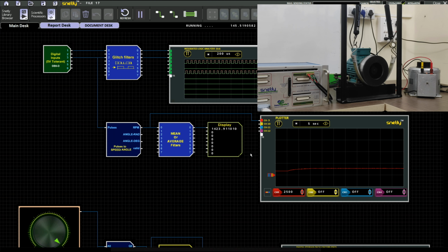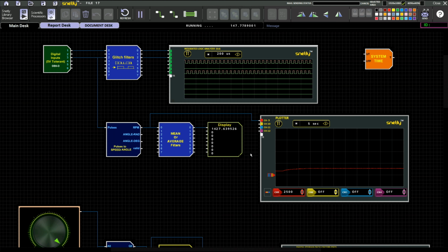Now the application is running in real time. We can observe here the encoder signal as well as the speed of the motor, your reference signal and the current waveform of the particular application we are using. Here we are using a 3-phase induction motor drive, so our reference signal will be sinusoidal. So the waveform we are getting in the analog signal is sine. Majorly we have done 3 steps: one for the measurement of speed, second is PWM generation, and third is the current measurement.